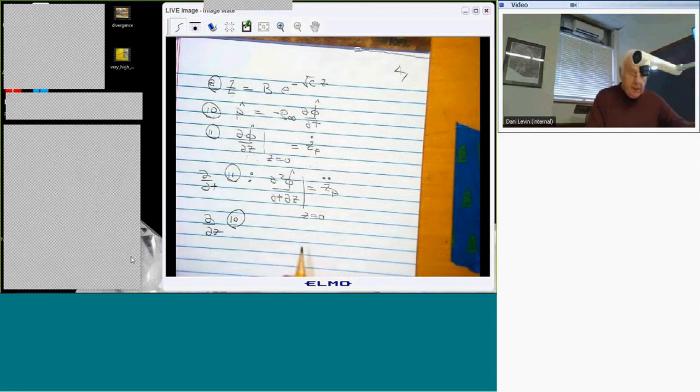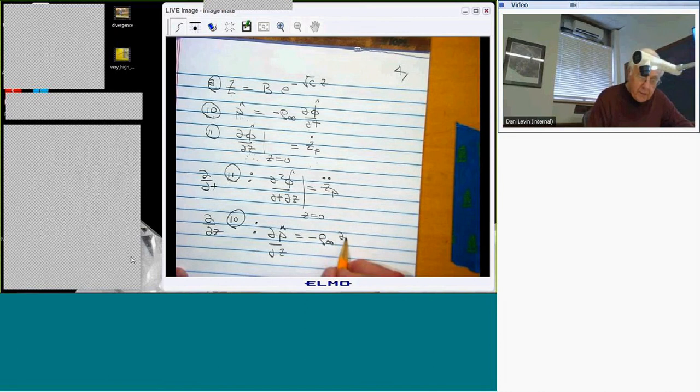And so if I do that, then I'll get dp hat dz equals minus rho infinity times the second derivative of phi hat with respect to z and t. Now, I'm going to make a bold assumption that a mathematician would worry about, but I'm not going to worry about it. And that is, I'm not going to worry about the fact that the order of differentiation with respect to z and t matters. I'm going to assume that everything's smooth enough that either way is okay.